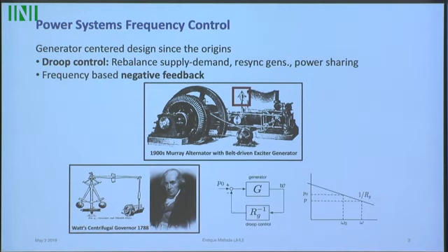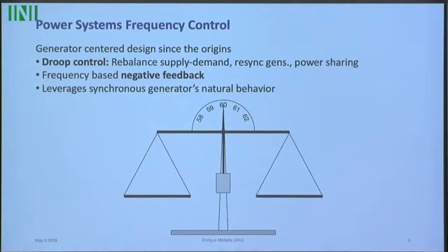So if you see the frequency going up, then you're going to go down on the power that you give. So higher frequency, lower power. It's a basic idea, and the reason I think it's still there and being used is because it works really well, and it also embraces how a synchronous generator works.